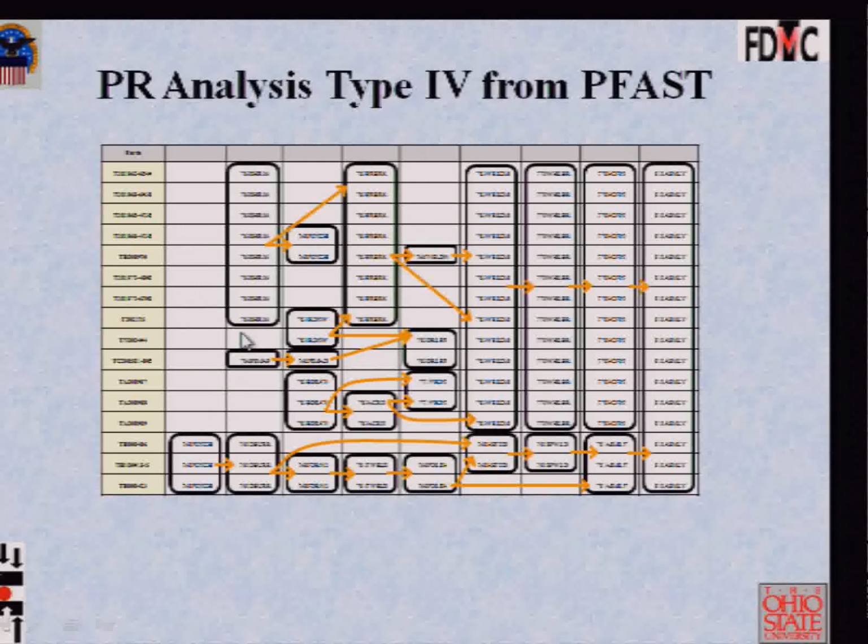So just look at families of parts, look at first op work centers which are common in their routings. That's a logical basis for locating inventory storage points. Second, part 2, where to locate the supermarkets to store kits of parts for different sub-assemblies. Once again, it's a no-brainer.